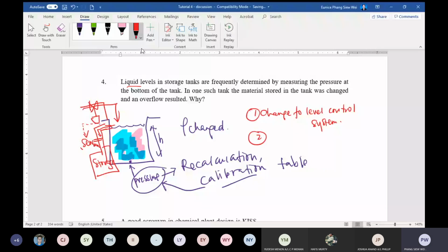And you know you won't waste chemical, because whatever goes to the storage is still in your storage system. You won't have that overflow. But at the same time, you have a safeguard here. So the moment there's liquid coming in here, your sensor gets triggered, you close the valve. That's another way to do that. But the easiest way, of course, is this one. Okay? Simple. Very simple.